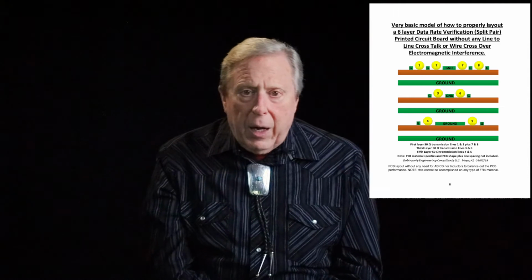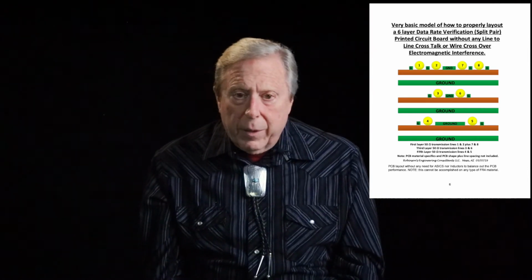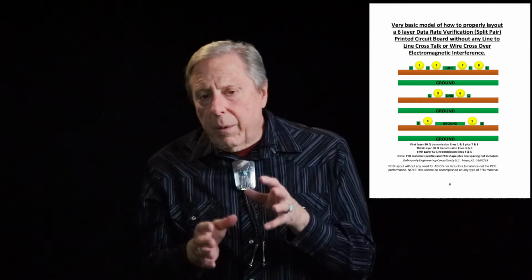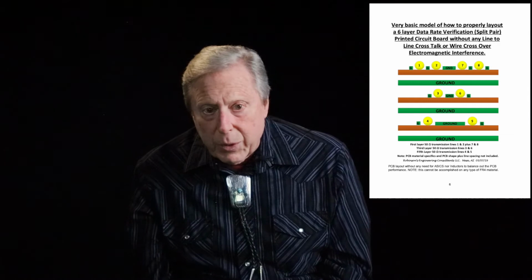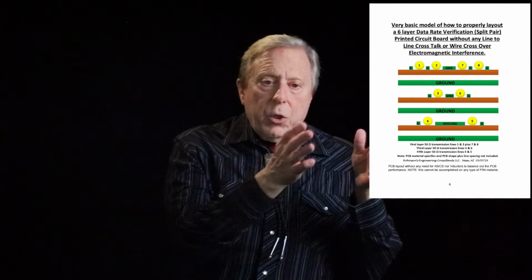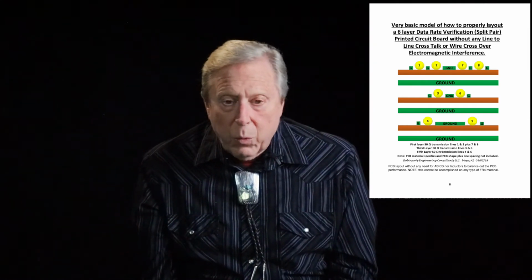Now 4 and 5 and 7 and 8 can be used for transmitting power on. So you want those lines separated because power talks to itself. So if you put 2 positive powers together and 2 negative powers together, they're really not doing what you wanted to have. What you wanted to have was power and return on the same path.